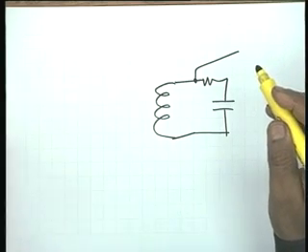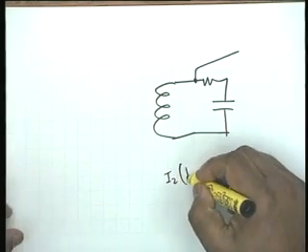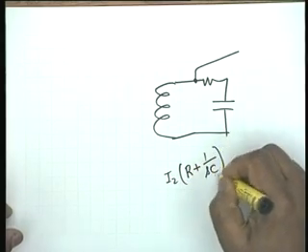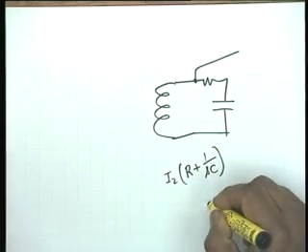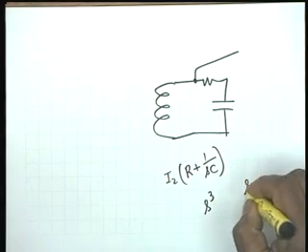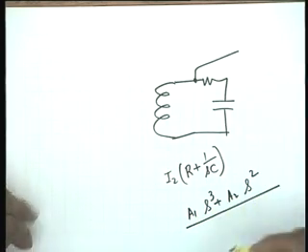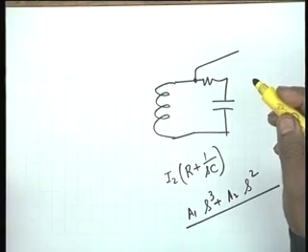Then, should I simply multiply I2 by SL? No, because there is an effect of mutual inductance also. The simpler thing would be to take the output as I2 times (R plus 1 over S), and then you calculate. Therefore, in the numerator you would have an S cubed term and also an S squared term. You will have (A1 S cubed plus A2 S squared) divided by a quartic polynomial, because of the 4 complex conjugate poles. Now, what can you say about this equation?